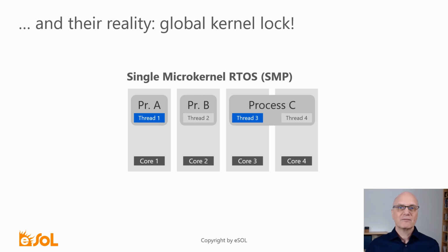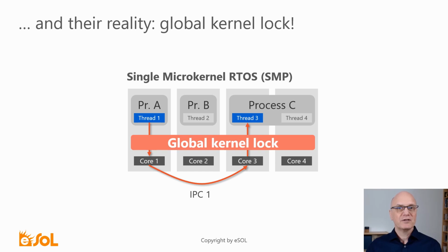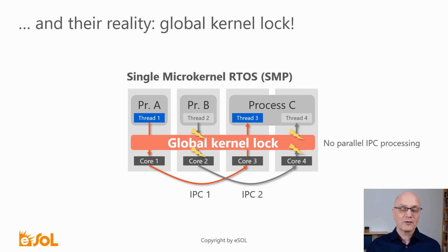configuration. But here is the problem with today's microkernel RTOSs on multi-core hardware. To maintain the necessary determinism with traditional operating systems, the other cores are blocked during inter-process communication, IPC. Cores are prevented from executing further IPCs themselves, and in addition, thread states may no longer be changed on all cores. The latter means that a waiting thread cannot be put into a running state. Therefore, all other cores, even those that do not want to communicate, can run dry and thus also stop. Without this block, these cores would change the system status without the communicating cores noticing. The problem was caused because microkernels were designed and optimized primarily for single-core MCUs over the past century.